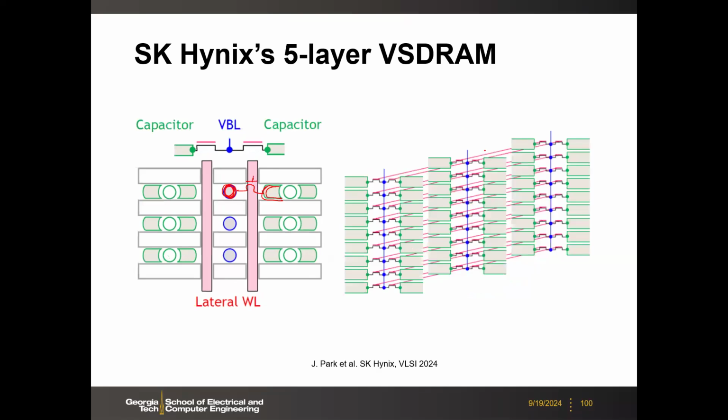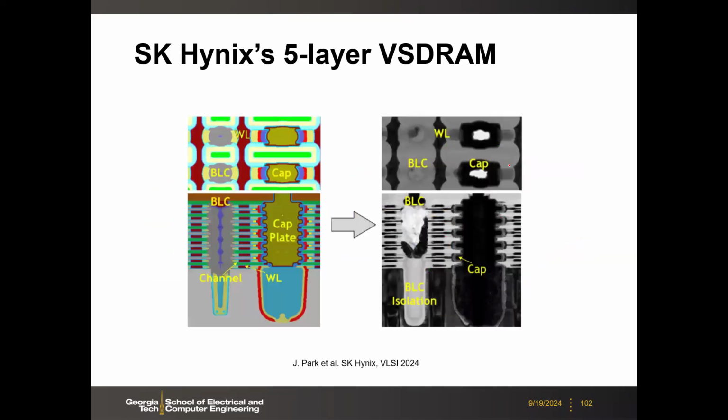It's like this one vertical bitline shared, and then horizontal 1T and 1C. Okay. So you can stack many layers. And here are some real images from this prototype. So here, the 1T is here. This is double gate 1T, and then 1C.